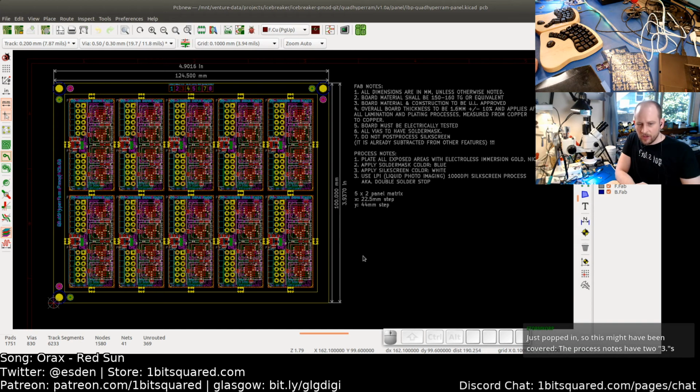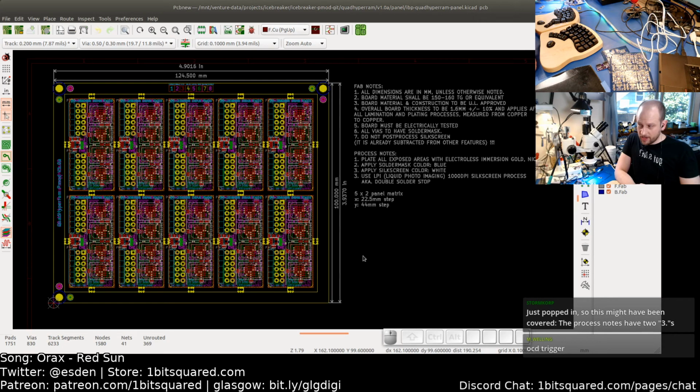But all it did is put the Gerber files in multiples onto one sheet, and then marry several different boards together into one panel. It didn't add tabs at all. It didn't add a frame. It didn't add fiducials. Well, you could add fiducials, but it was annoying.